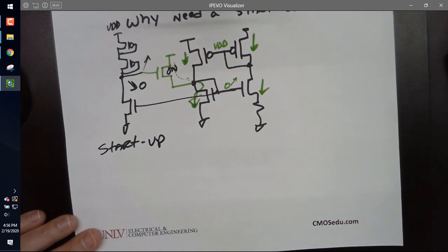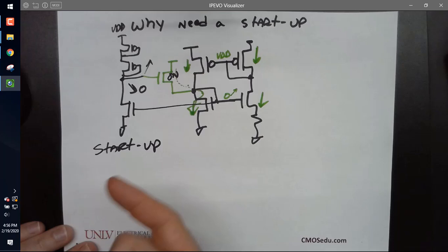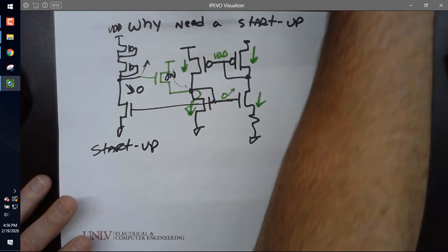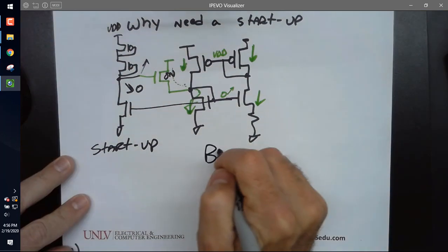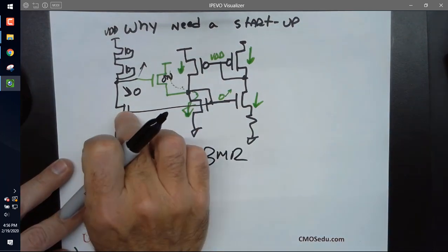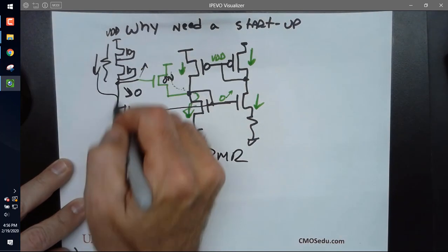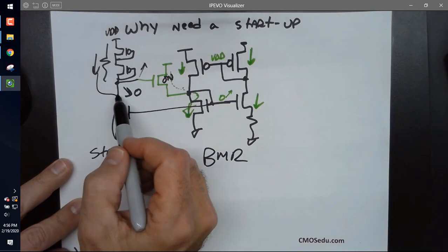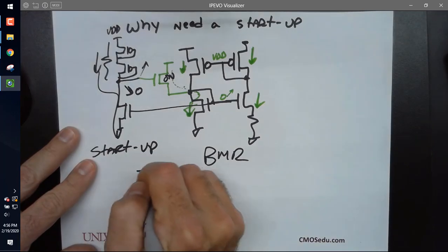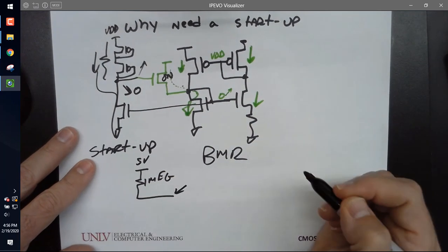Okay, so you agree once it shuts off that there's current flow, or once the beta multiplier turns on, that there'll be a current flowing in here? There's a current flowing in here, and I make this resistance big enough, that the voltage drop across that from this current flowing in there will drive this node to ground. So wait, let me do it simpler. Here's 5 volts. Here's 1 mega ohm. If I ask you, what is this voltage? What's the answer?